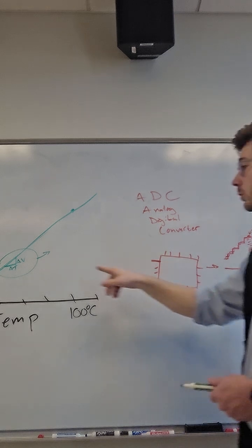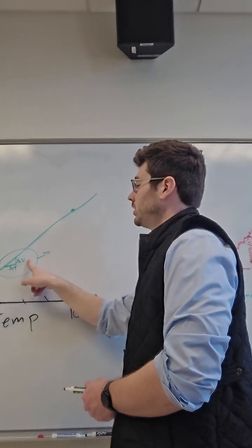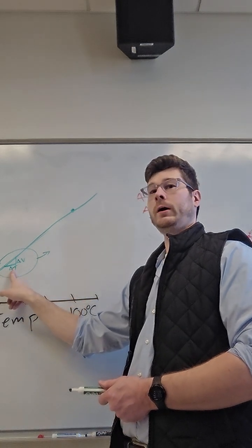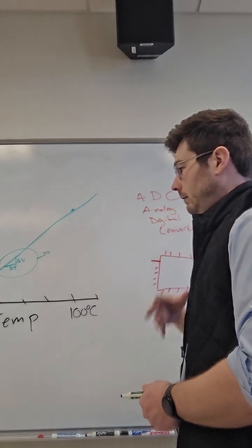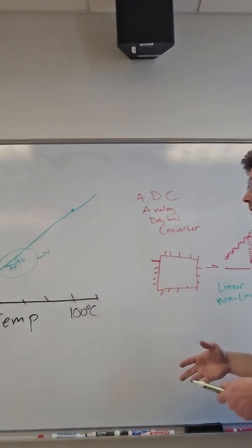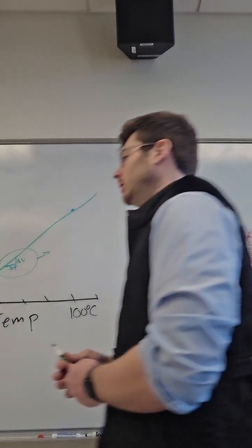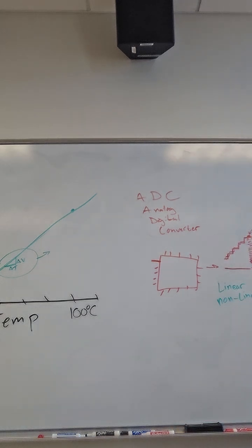And then you would look up on the data sheet, okay, this much change in voltage means this much change in the thing that you care about. You can program it in that way. Or you could test it. Like I said, you would have an environment, like a calibration gas at a certain concentration or a flow rate that was calibrated and known, that you could turn on and off to calibrate yourself against, all that good stuff, where you could teach your system to be accurate, because that might be important.